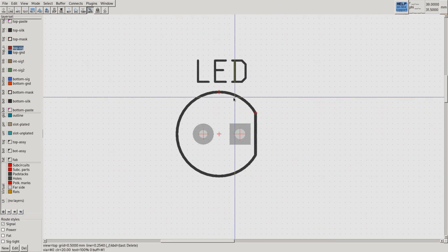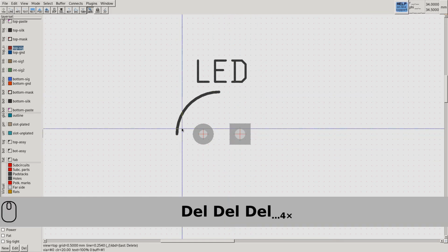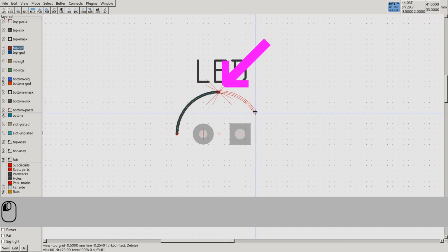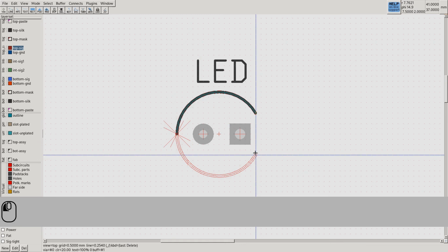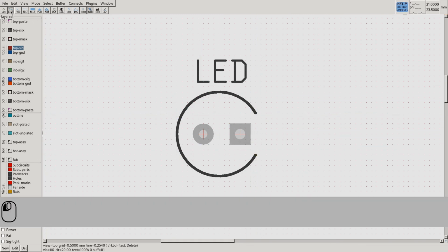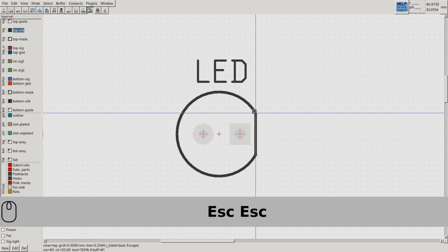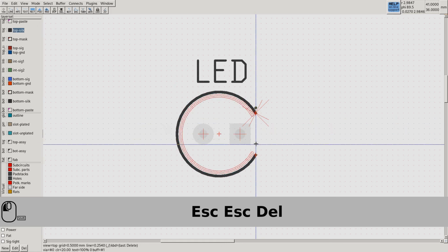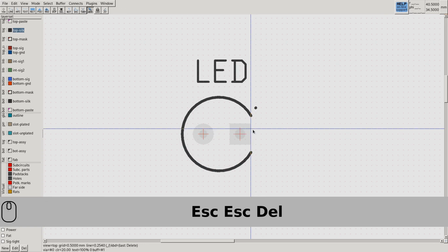But there is yet another much simpler way to do it, and probably the one you want to remember. So let's remove the existing arcs. Let's keep the one arc and say this is the one we drew. And instead of drawing additional arcs, we just take this one, grab the endpoint, and just drag the endpoint up this way. And now we have both endpoints on the right points, and we just have to draw the line, which is then finished. And if you drag this endpoint and press Shift, you can actually change the arc diameter, and this makes it a lot easier.